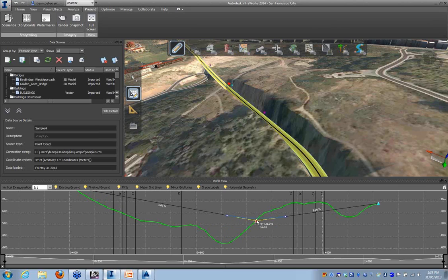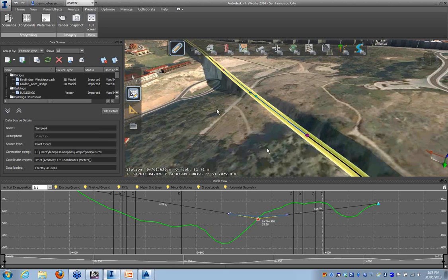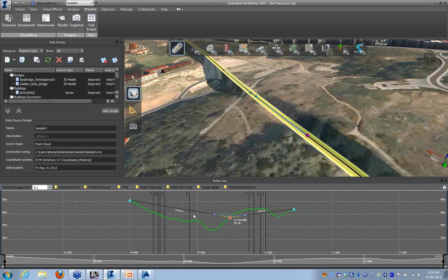Change the elevation of the road. If I pop that up in there, because we're going to get a lot less cut, we're going to have a great big slot over there, or we can put in some more PVIs, etc. So now we can play around with this quite a lot. We can also export the whole thing to Civil3D, and it will take the alignment of that road, and it will also take the vertical geometry as a profile through to Civil3D.